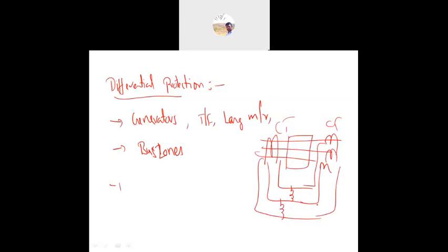The current entering the machine winding and leaving it is measured by the CTs. Whenever there is a variation, only then does the relay coil trip. Under normal condition and during an external fault, the current entering the winding is equal to the current leaving.